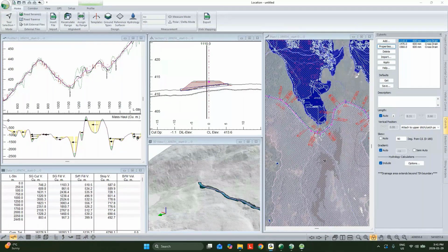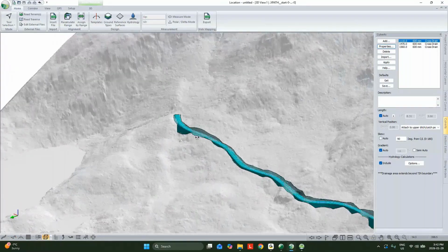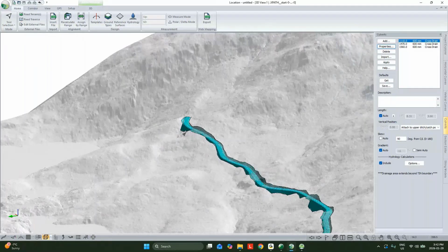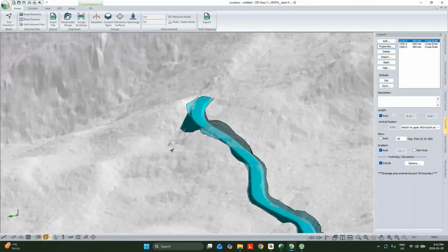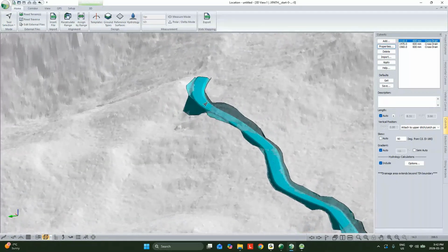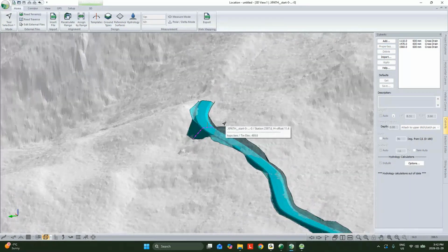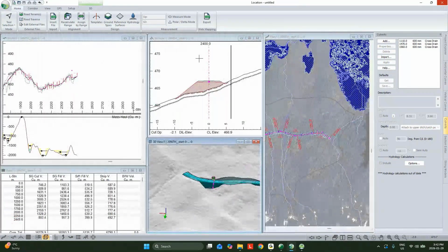All right, so landings. Like a lot of other things, there are a few different ways we can tackle them. And just to reiterate here, I just went the easy way, basically planning the deck wood on the native ground. But if we wanted to have that actually graded out, we could. I think the two broad buckets would be, well, maybe we want to just have it as a road widening, so not worry about any grading and location. Just come in here and we could say, well, maybe we do it as a wide template.